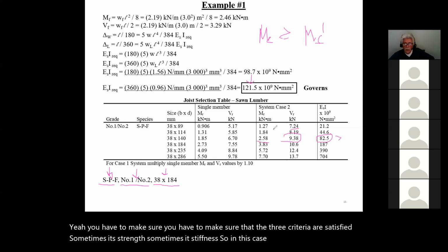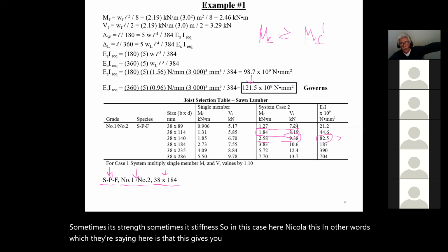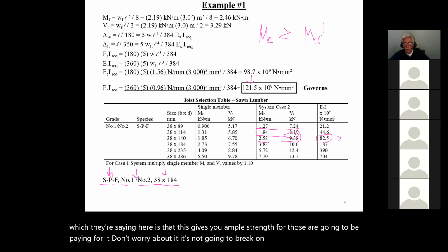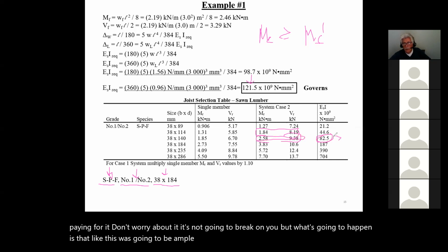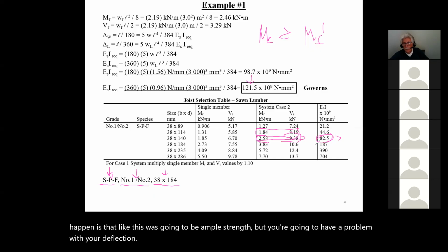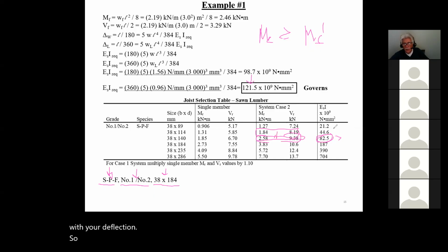Nicola, what they're saying here is that this gives you ample strength for the loads you're going to be putting on your floor. Don't worry about it; it's not going to break on you. But what's going to happen is that, like this one's going to give you ample strength, but you're going to have a problem with your deflection. So it's good for strength, no good for serviceability.